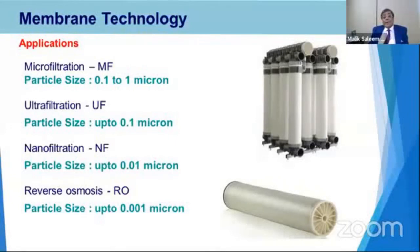That is why all RO membranes are tested on sodium chloride, to see how much rejection capacity they have. When you see the data sheet of RO membranes, they will show you the rejection of sodium chloride, such as 99.7%, 98% or 99.2%. That is how they are tested.